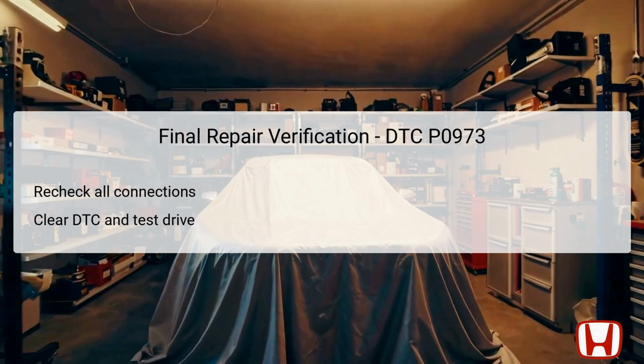After completing the necessary repairs for DTC P0973, it is crucial to perform a final repair verification to ensure everything is functioning correctly. Begin by rechecking all connections thoroughly to guarantee there are no loose or damaged wires that could cause issues. Once confirmed, proceed to clear the DTC again using the HDS, preventing any old data from impacting the results. It is important to take the vehicle for a test drive in various conditions to ensure the transmission shifts smoothly without triggering the DTC again.